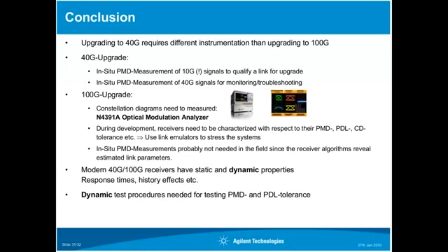What people are normally characterizing for an optical link is the average PMD, or the PMD coefficient. Let's say if the PMD coefficient is 10 picoseconds, that is basically telling you what kind of variations of the differential group delay you will see. So assume your link has 10 picoseconds PMD, then if you take a look at your link now, you probably can see 20 picoseconds. You can sometimes see 30 picoseconds. 30 picoseconds is probably not so frequent.